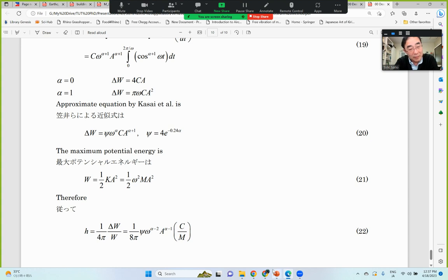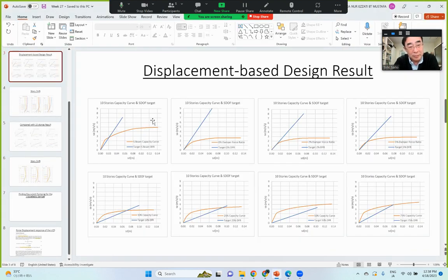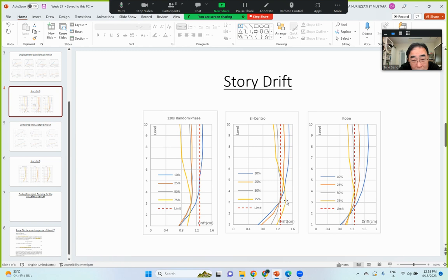Okay. I also ran again and checked the calculation from last time. This one is for the 10-story. This is the steel beam, and then we check from 0 until 75%. The damper is adequate at 50% and 75%, and when going to 75%, the straight line goes up a little bit. It's probably due to this action here.